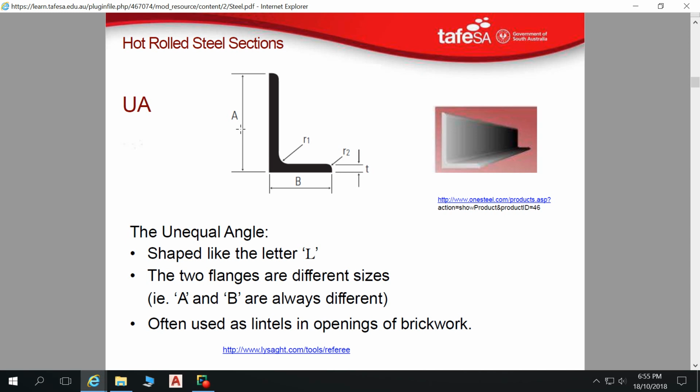But then, as we look outside the window, our balustrade there is made of flat bar with flat bar tops. Look across there, we've got these columns that are created by universal beams with equal angles as webs, and some flat bars in there for web. Actually, no, they're equal angles as well.